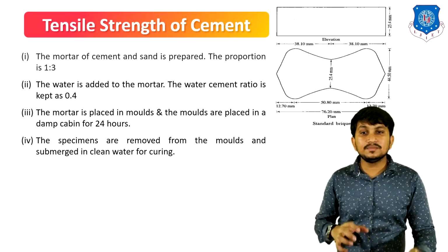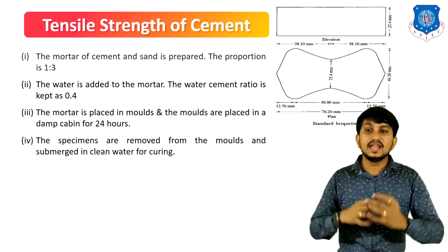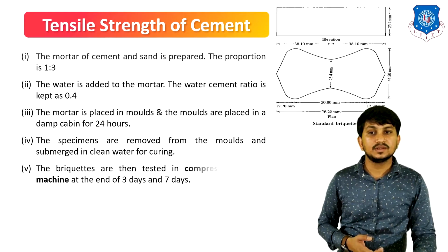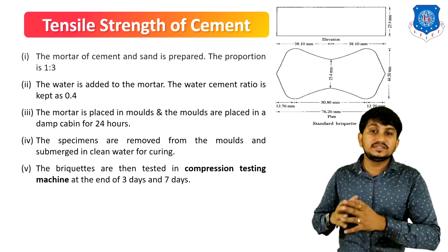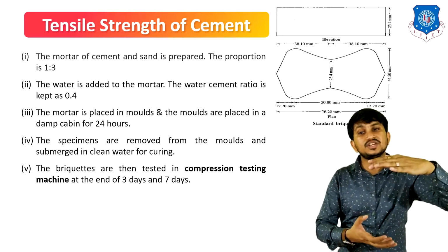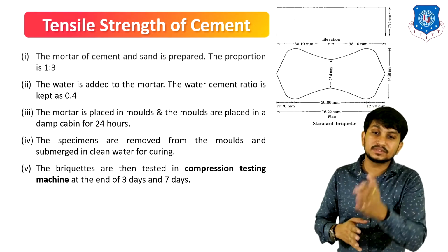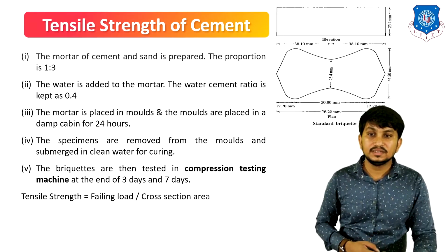The specimens are then removed from the molds and submerged in clean water. After curing, the briquettes are tested in the testing machine, which was shown earlier, at the end of 3 days and 7 days.